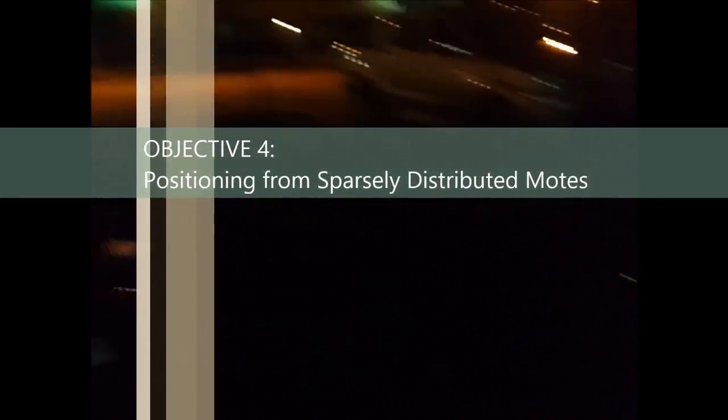Okay, so I've set out all the motes in a configuration similar to what you're going to see on the screen here. And then I'm just going to plug the base station on. It's connected by a serial link to the laptop. That will send the data into MATLAB. It'll send the distances that the base station calculates for these motes. I've put in the coordinate positions to match the configuration, and I've also set up the grid based on this measuring tape. So I've created a small grid.